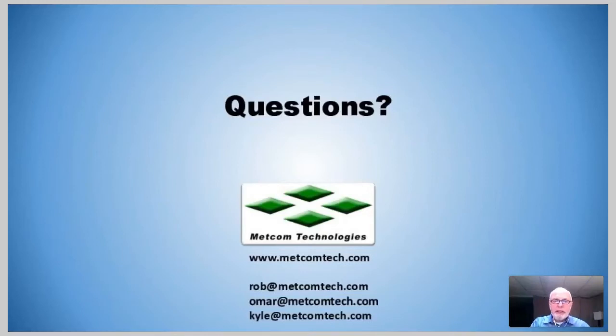If you can increase your grinding circuit efficiency, there are three things that you can do. The first thing would be to say, okay, let's run the same ore, the same tonnage, the same grind, and let's reduce our energy consumption. You would do that by reducing your ball charge level. Then you would save money on grinding energy and grinding balls, and those are a huge cost in your plant. So that's always an option if you increase grinding circuit efficiency, whether it's by increasing CSE or any other method.